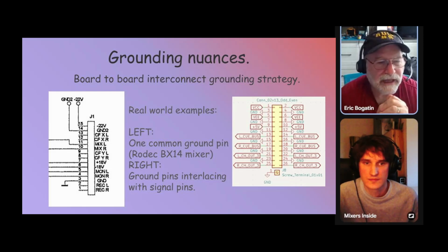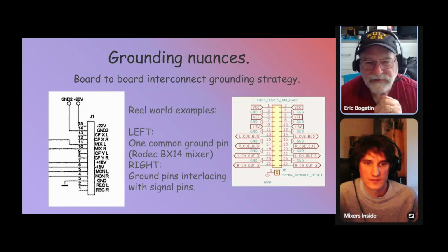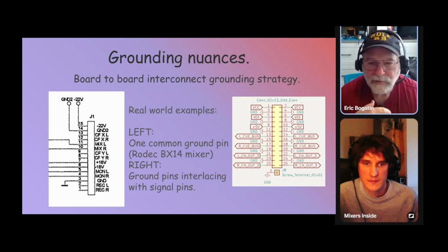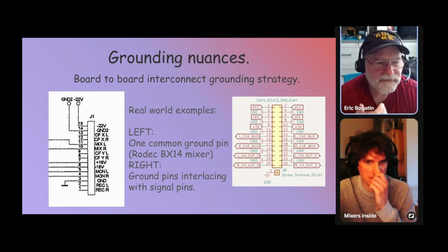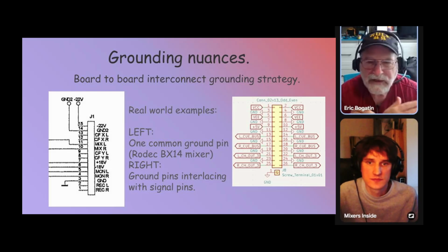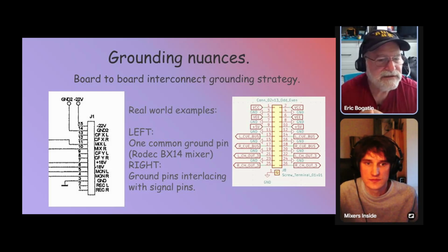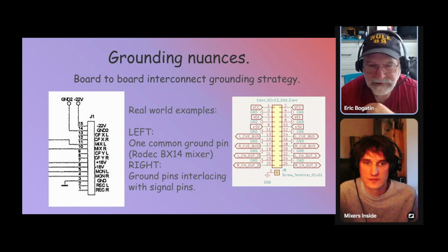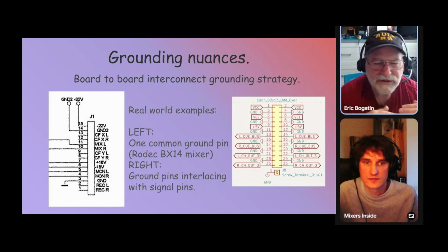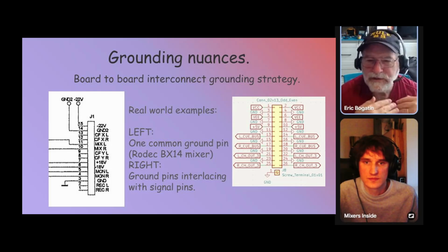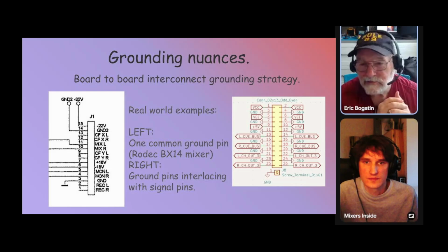When you have something like on the left, all the returns are flowing through that one pin labeled ground. It's not ground, it's return. All the digital signals' returns flow through there, so you have a lot of crosstalk with the digital signals, and all of the analog signals see that same return path as their reference. Even though it doesn't have much current flowing through it, you have voltage noise on that return path, and you see a huge amount of crosstalk.